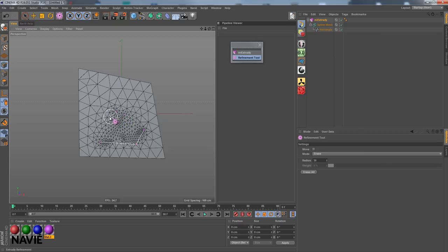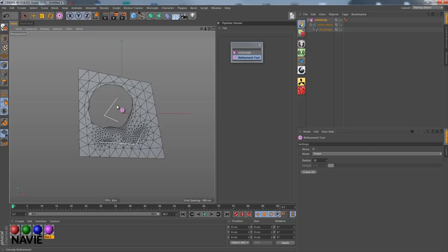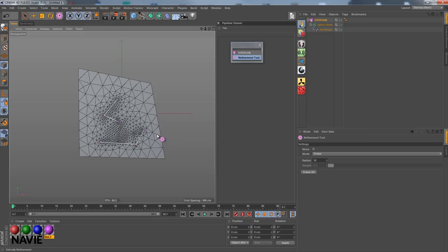If I do it like this, put it on the other side, we get kind of a degenerated effect here, and it gets worse. That's because the flow is now in the other direction, so against the flow of the outline. By shift control clicking and then moving, we can just reverse our sequence again, and it becomes the correct refinement.